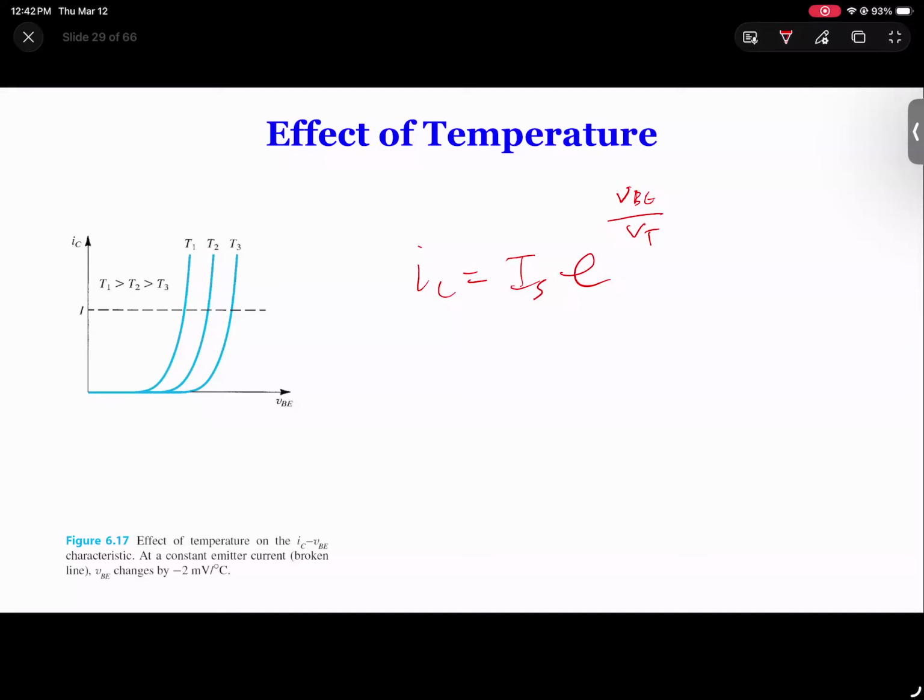So your VT actually changes. But not only the ambient temperature changes, but also the circuit around it. When you design a system, it creates heat with the losses, and that heat will increase the temperature of the components inside some sort of enclosure or on your PCB. And sometimes, like in military applications, they want you to be able to handle 150 degrees C temperature. So this number of VT is going to increase dramatically and your current actually reduces dramatically. So that's something just to keep in mind.